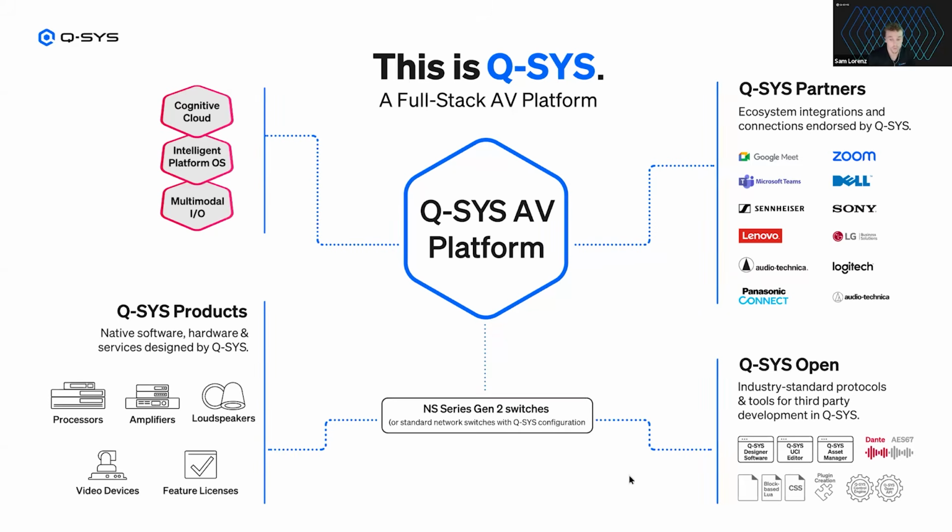We have Q-SYS Asset Manager, which we still do have, but we are now transitioning to what we're calling Q-SYS Library, which is an online, web-based asset manager where you're able to grab any third-party plugins that we support or any plugins that help the functionality of your system. You log in to your library and check out any plugins that you want. You then go into your Designer 10.1 and above, log in through that, and you'll start seeing your plugins auto-populate. So we're now managing our plugins through a web-based library versus just an asset manager, which is only in Designer.